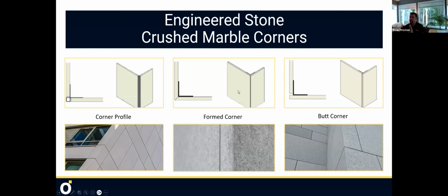We can fuse these corners together and actually do nice corners, place that L or U element on the wall, and then change the body to make sure that we're level and plumb, right? You put that corner on first and you fix that problem. And then you work your way into inside corners, which are a lot easier to fix than outside corners. And if you're really out of plumb or really out of plane somewhere, then we can fix that with these types of corner pieces.